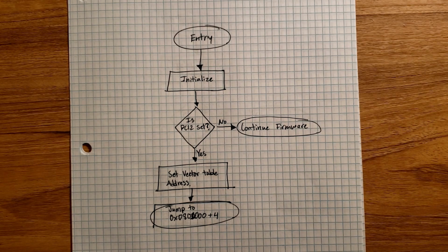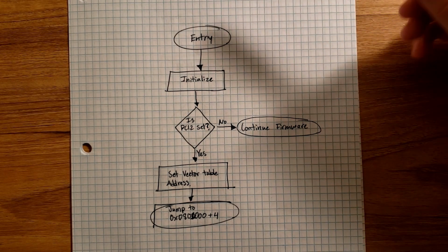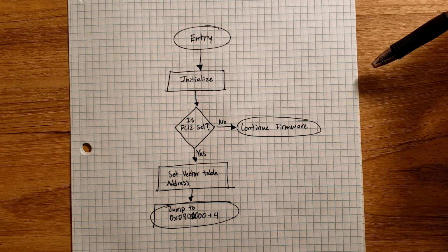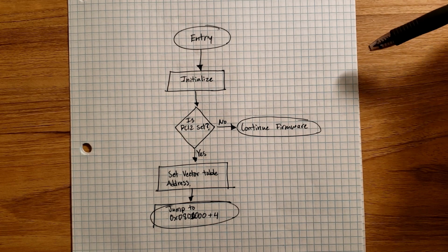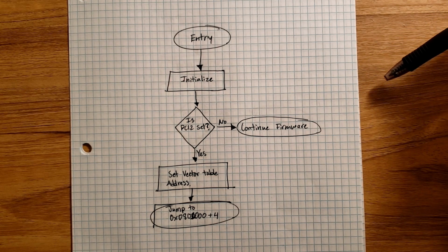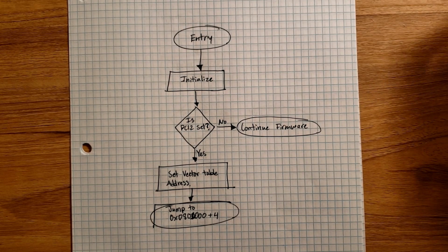The problem that we have is that interrupts from the primary firmware, which have been initialized here, are still being triggered in the secondary firmware. So you have a bunch of pending interrupts that can't be serviced because their interrupt handlers aren't there anymore. And so your SysTick interrupt gets held up and never gets serviced because it's the lowest priority. So that means in our secondary firmware, the LED does not blink, and that's an important thing. And I definitely wanted to do it the right way.